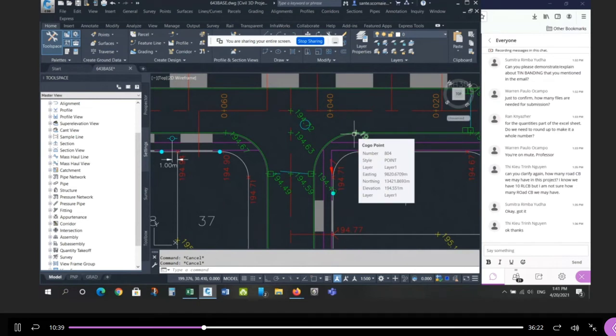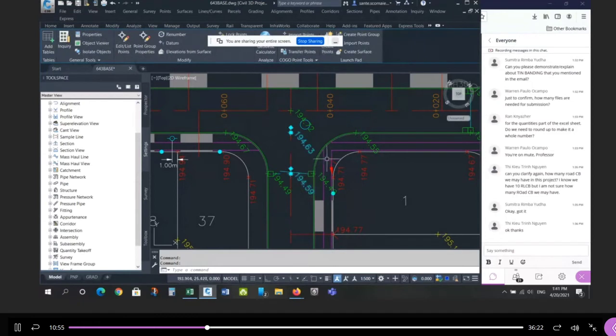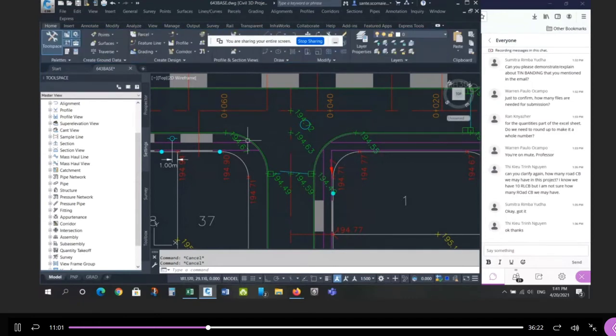This is like a high point on the gutter. It's falling here and it's falling away this way. So that's a high point on the gutter, but it's not a high point on the road. It's just the way the geometry works out on the gutter lines. Because this is falling down, right? Remember the edge of this is higher than this. So it turns out that this is higher than this when you come around. So the gutter wants to come around here, flow to here. The gutter wants to come from here down and from here down. So there's an argument for you don't really need a double catch basin from here because there's not a lot of water coming from here.